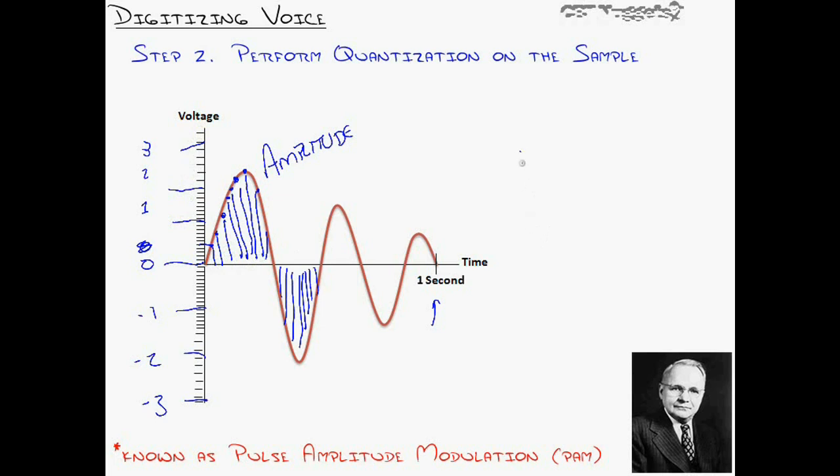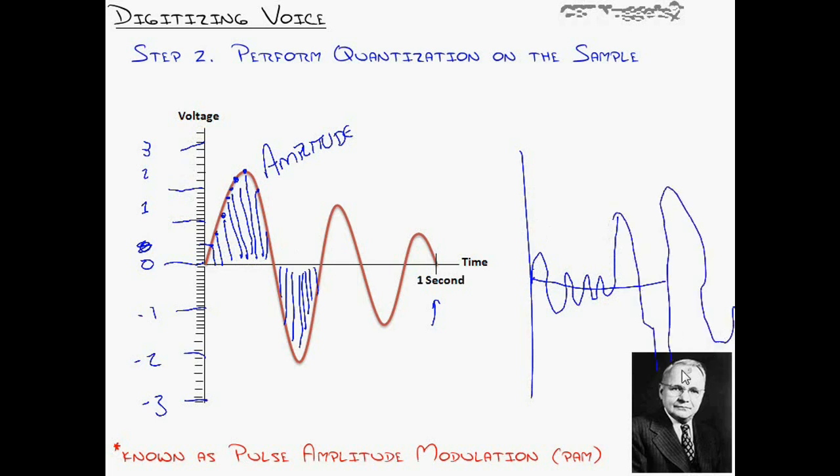When you're speaking with human voice, like take my scale like this, most of the time I'm going to be up here, and if I get really loud or really high pitched, it's going to shoot way up and way down. But most of our conversation is right around this close to the line, or close to the 0 scale. So by taking more samples down here, we can get a more accurate reading, or more accurate quantization level with each one of these lines, than if we would just space them out evenly.